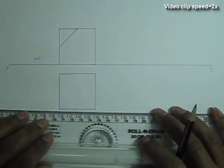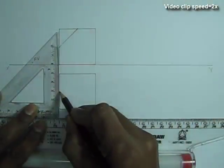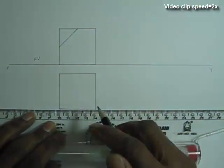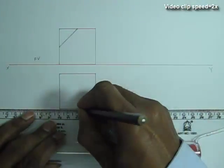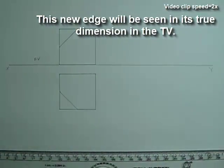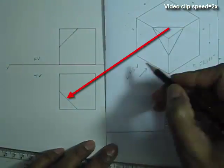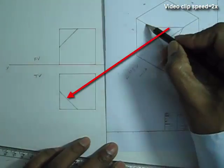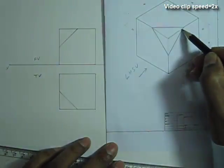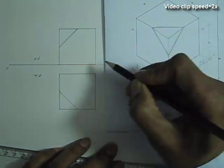Now we will show the new edge that has been created. So the midpoint of the edge and the midpoint of this side, we connect these midpoints together. So this new edge will be seen in its true dimension, and the inclined edge is projected. So it shows the projected length of the inclined edges.